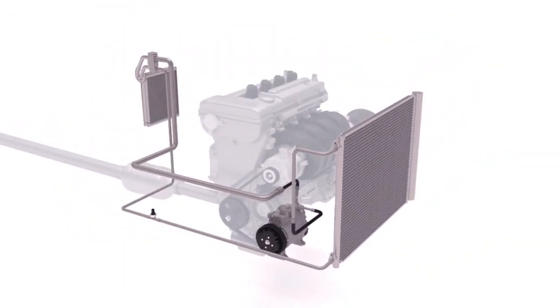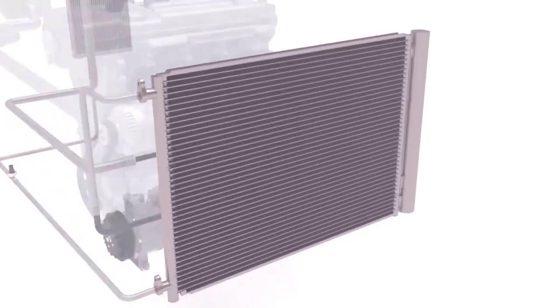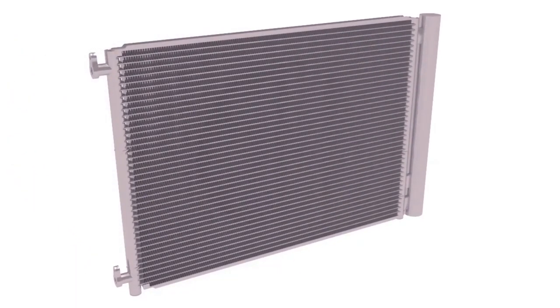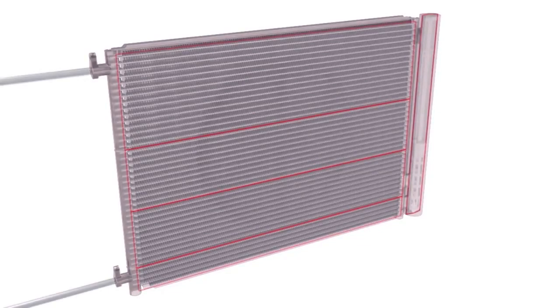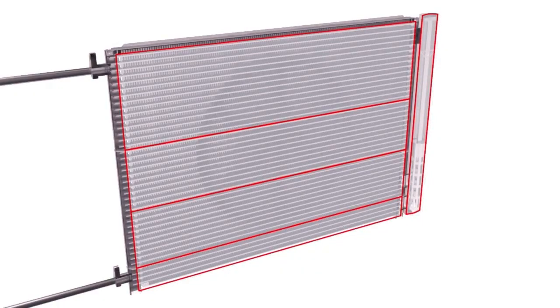The Denso subcool type condenser operates using the same principles as a domestic radiator, because the condenser transfers heat to the air. The condenser is divided into four main sections: a gaseous section, to remove the heat from the hot gas, a condensing section, a gas-liquid separator, known as the modulator, and a subcooling section, with the high-pressure refrigerant flowing through these four sections in that order.